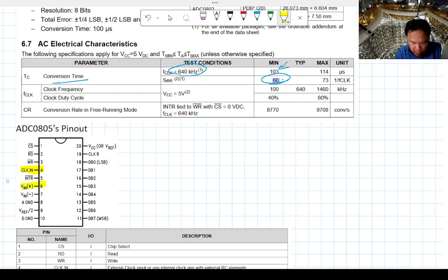These are the inputs, right? V in, V minus. One neat thing is that it does a second reference, so it runs from 0 to 5 volts, but it also wants a voltage divider that gives you exactly 2.5. So you want to pick those two resistors very carefully so they match each other. You have your voltage sources. This is your analog ground. This is your digital ground, because those could be different.